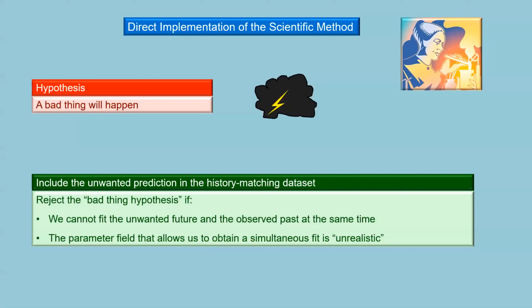And if PEST needs to introduce connected permeability to make a bad thing happen, by God it will. And it's up to us to say, oh, that's too connected and the permeability is too high in order to reject a hypothesis. It throws responsibility back on us. It introduces subjectivity to the decision support modeling process, but it was always subjective because by now you realize there's so many decisions we have to make about appropriate simplification, appropriate parameter abstraction, and things like that.